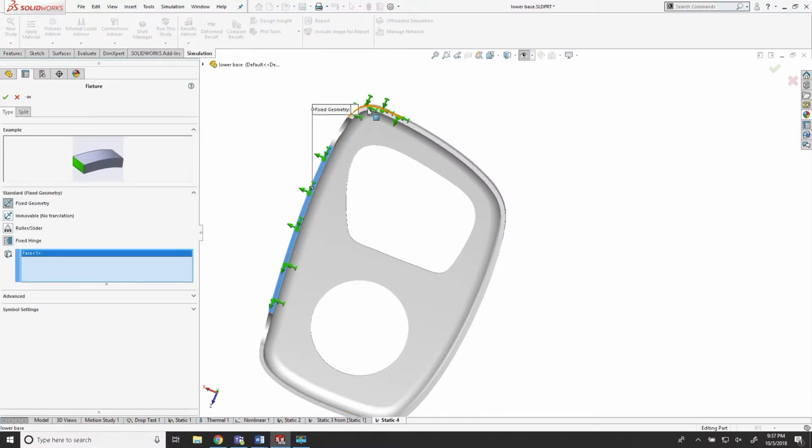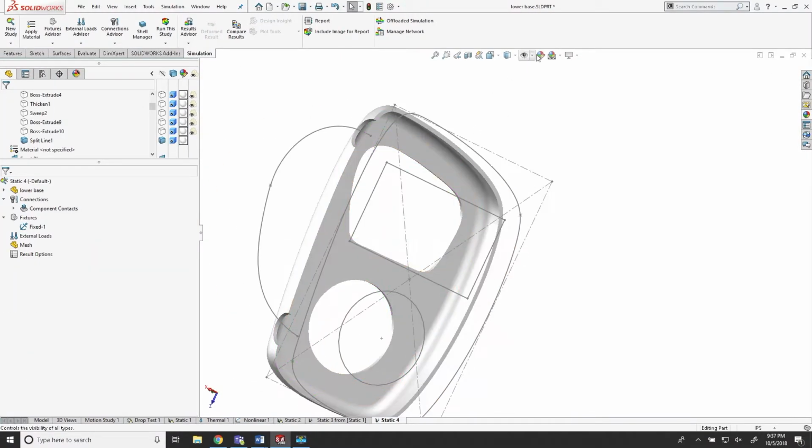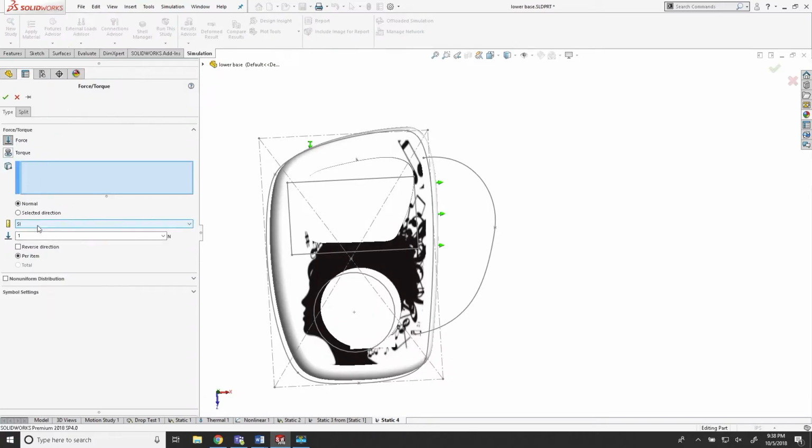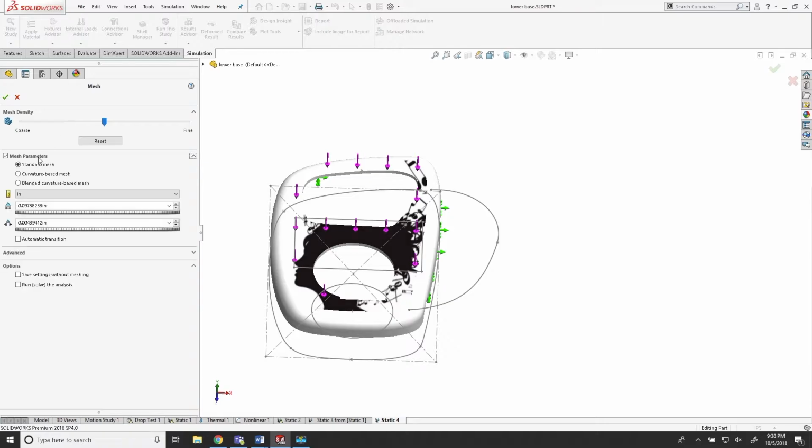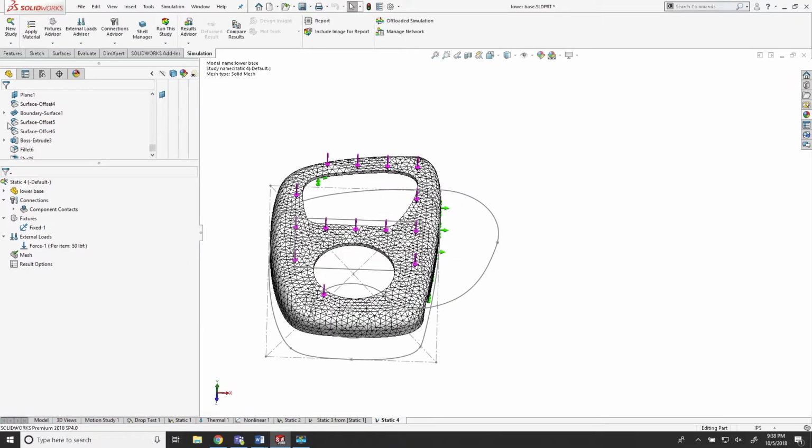For our toy, we want to check our design from a static load. We'll describe a known force. We'll add some mesh refinement for accurate results. It's just that easy. We do the mesh, boundary conditions, and context, and SOLIDWORKS simulation gets us results, and fast.